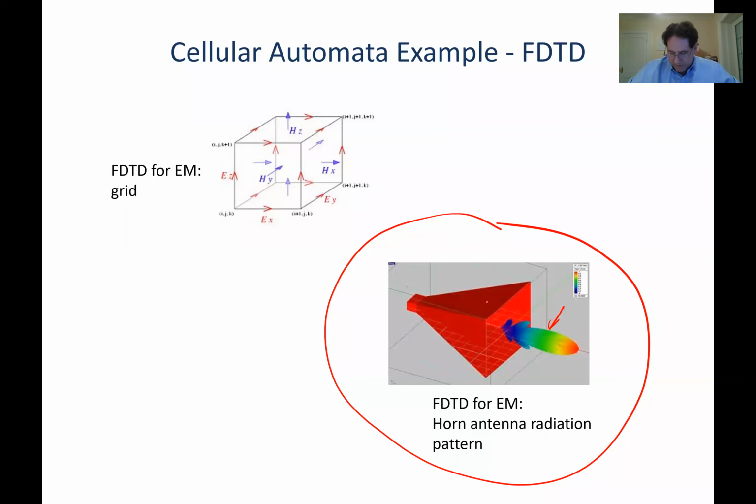And basically by stepping forward in time across every point in this whole volume and updating the electric and magnetic fields in sequence, I can work out in both space and time what the electric and magnetic fields look like for this particular geometry. And this is one that's way too complicated for you to solve analytically, just by trying to solve Maxwell's equations with pen and paper.